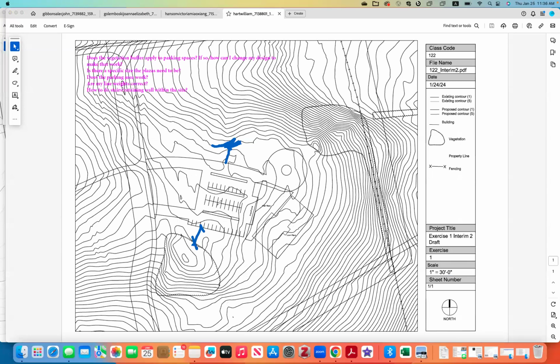No, there is no specific size the plaza needs to be. For now, I would say, no, in this area it is a little too small. Again, coming back to the talk about the swale, you need your swale to flow along the front of the building, and you don't have enough space. Well, you have enough space to create a swale, but you don't want your full plaza to be a narrow swale. Okay, although the swale is pretty subtle, we still want to have some usable space in the plaza.